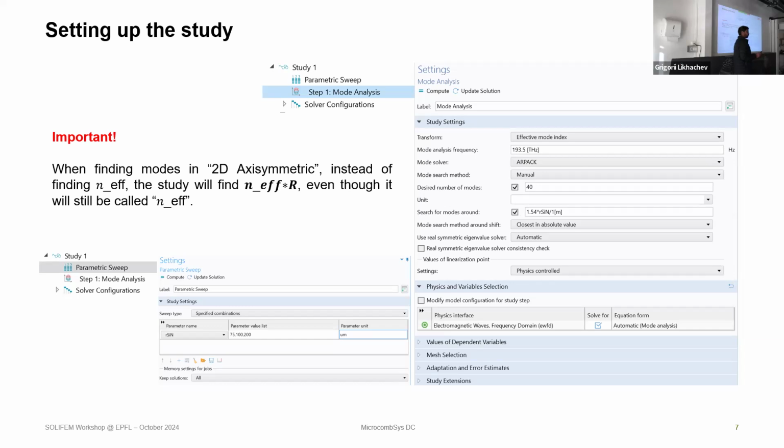Now another part here which is important, which is common with what Zian will say later, that you have to simulate for a very large number of modes. You have to be very clear here that if you make your mesh very, very fine, it will take a lot of time to simulate. So whatever mesh parameters I have added here, it's already tested. The whole simulation is with about 40 modes.